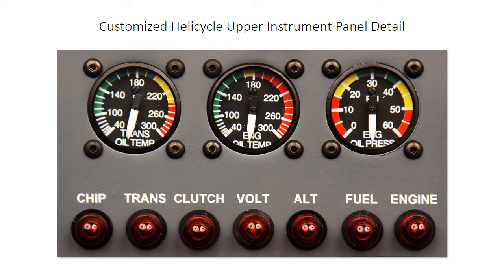And from the viewing angle that you would have sitting in your seat in the cockpit, the amount of light going up at that angle is not very good for LEDs. So they're very difficult to see, especially in the sunlight. These are much better, but you can also miss these. As you'll see later, that's exactly why I did all this. I had a low rotor warning and I didn't even notice it. The light was lit. It did not catch my attention, and that's why I wanted a Master Warning Annunciator that would be almost impossible to miss.